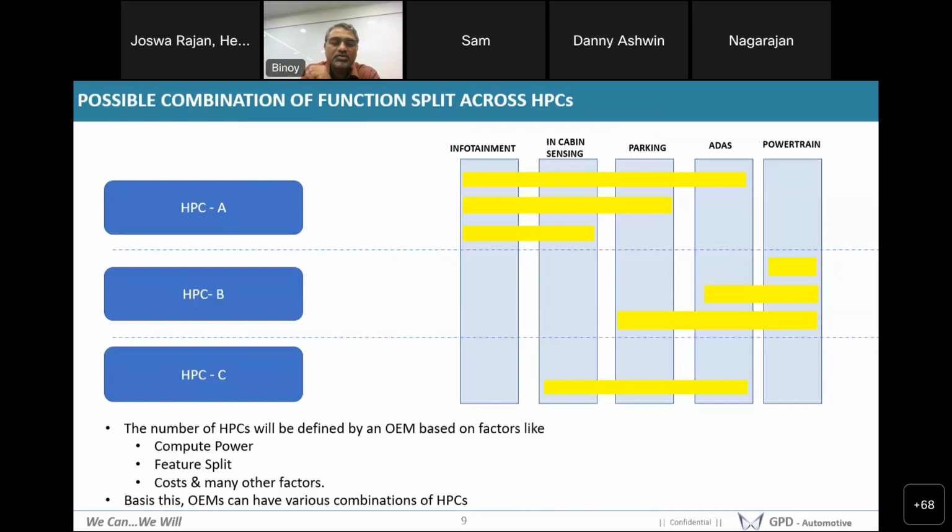Whatever the software architecture maturity we talk about, there is nothing like hardware separation in many things. So nowadays, HPC 1, 2, 3 get defined by way of grouping by functional safety requirements, which kind of drives this architecture. The software architectures are also available to create containerized solutions where you do different levels of functional safety containerized and still run everything on one controller. We have multi-OS systems, hypervisor systems. We can run Android, QNX, Linux, everything in one chip.